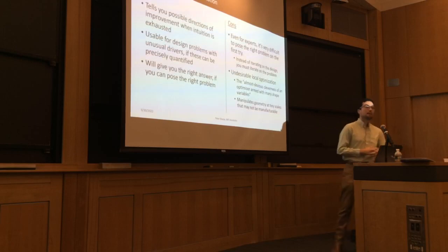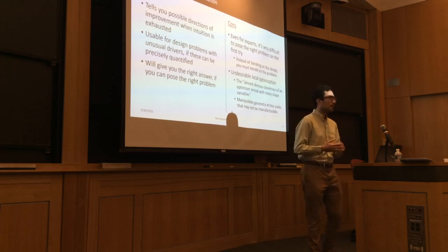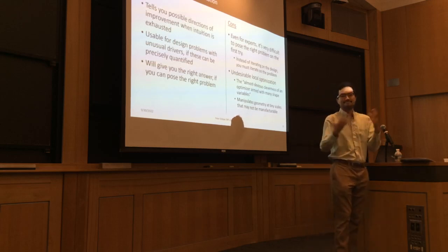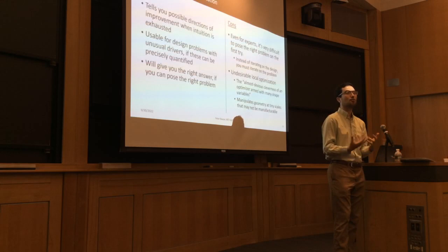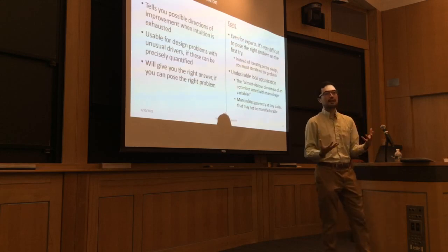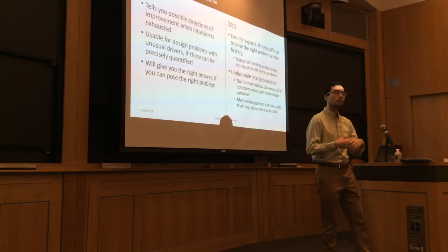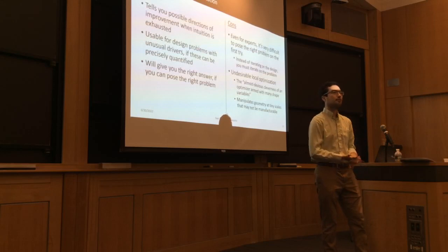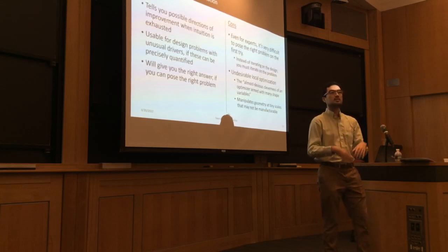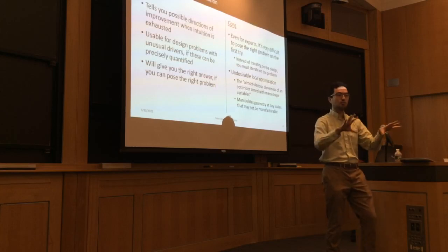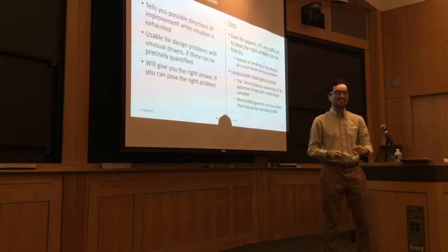So to summarize kind of the impact of this paper, in the 1990s, as I said, there was a lot of optimism about optimization. There was hope that this would be kind of a push-button solution that would eliminate the need for expert-guided design. But in practice, that's not really proven to be the case in the 20 years since. And so because of this paper, most optimization studies on real-world airplanes, rockets, airfoils now look at many, many points or think very carefully before giving the optimizer total latitude over exactly what to do, because you'll find these effects.